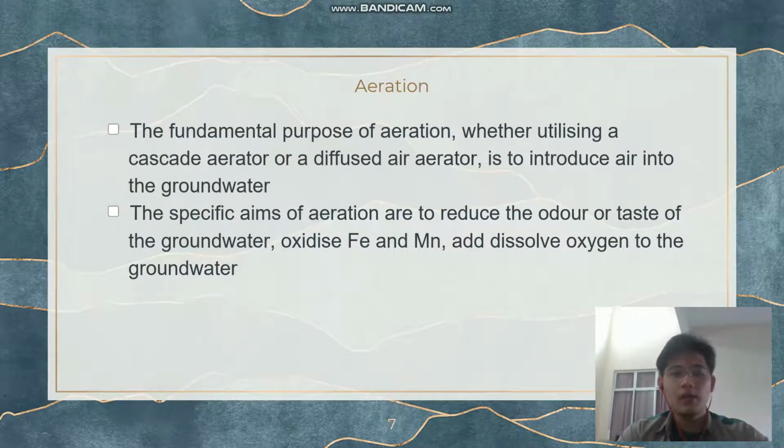Aeration. The fundamental purpose of aeration, whether utilizing a cascade aerator or a diffused air aerator, is to introduce air into the groundwater. The specific aims of aeration are to reduce the odor and or taste of the groundwater, oxidize Fe and Mn, and dissolve oxygen into the groundwater.